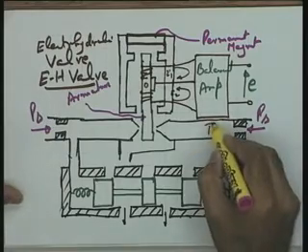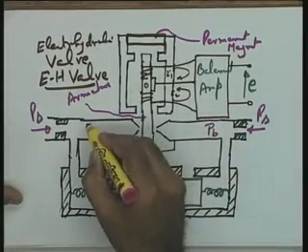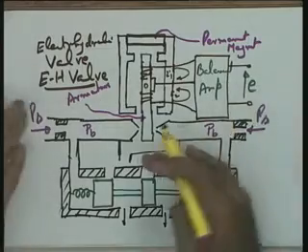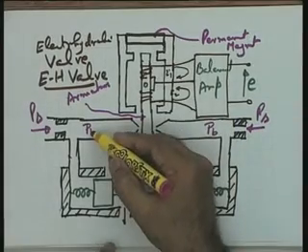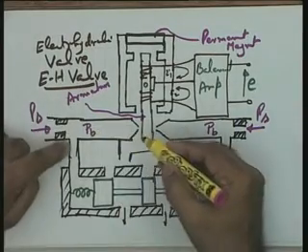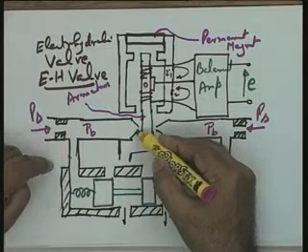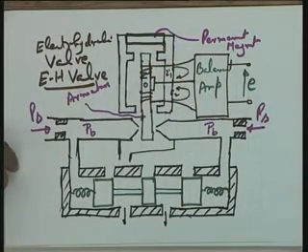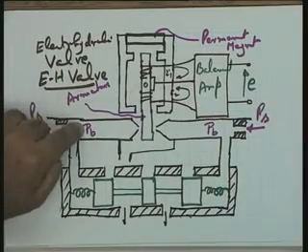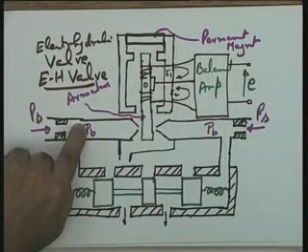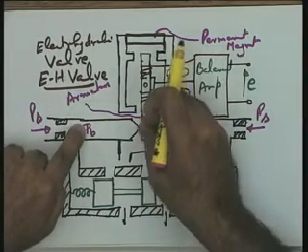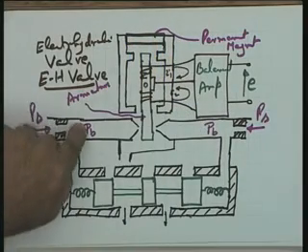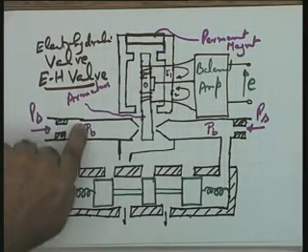The back pressure here, PB, and the back pressure here, PB, are going to be equal. I hope this is very clear, that you can control the pressure here by controlling this opening. If you move this flapper totally away from the nozzle, help me intuitively, what do you say about PB? Will PB decrease or increase?